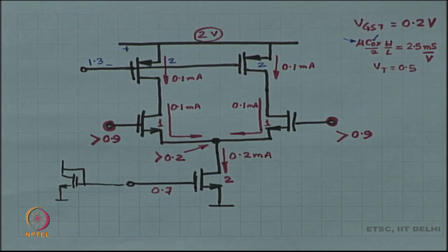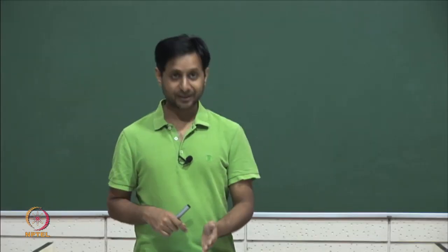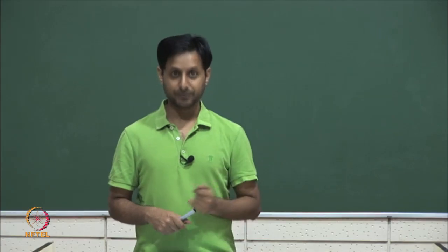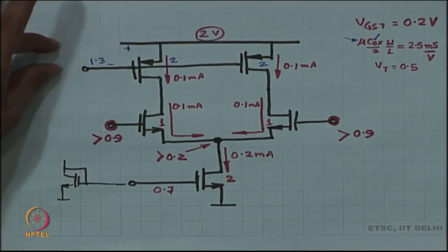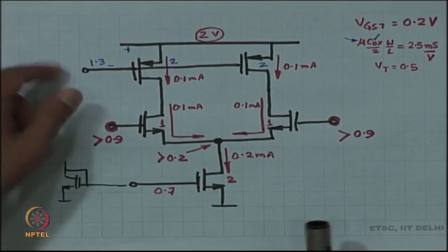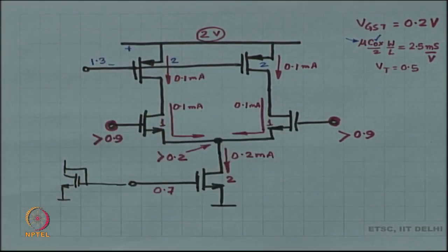No, no, right? I hope not, right? Do not use batteries over here. You are again going to use a current mirror. You are going to draw exactly the same amount of current through another PMOS, and that is going to mirror it.